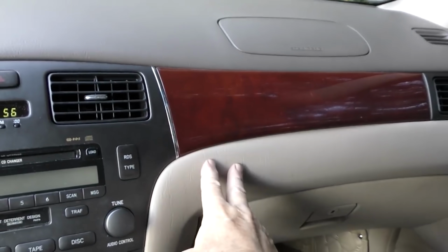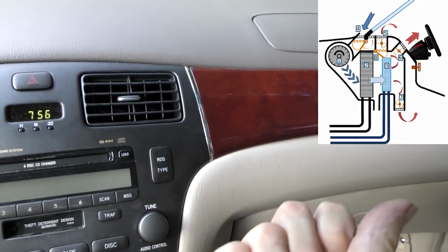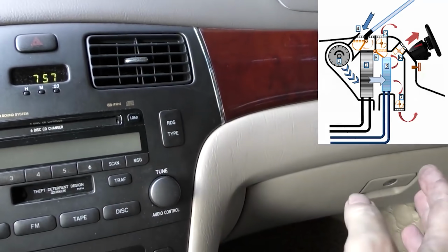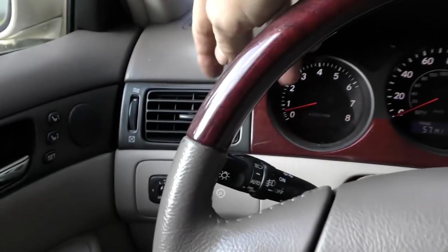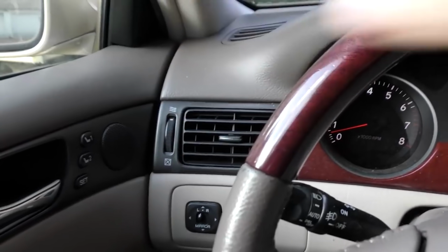And in that case, the passenger side would turn the duct to the heater open using the actuators that open the door, so you'd have hot air blowing here, but on the driver's side, it would only open the actuator for the AC system, so cold air would come out here. And you can guess what happens with computer actuated systems when they break. I mean, thank heavens this is a Lexus. They hardly ever break, so I don't have to mess around with it.